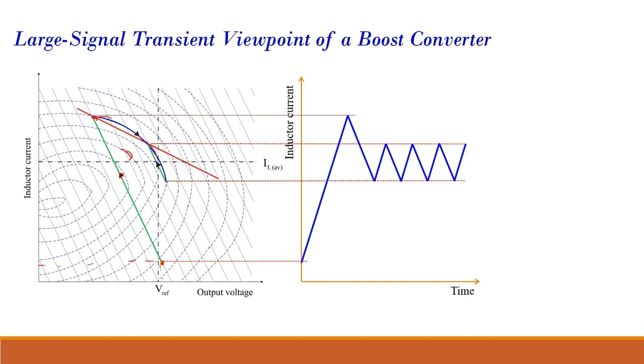Sir, this behavior is similar to the steady state operation and the time optimal control? Yes, that circle, they are the same. That circle, when it is operating in steady state, was for a buck converter. But for a boost converter, when it is on, it is a linear reduction, and then like this. When you solve the differential equations, you will get to know how it is varying with time.